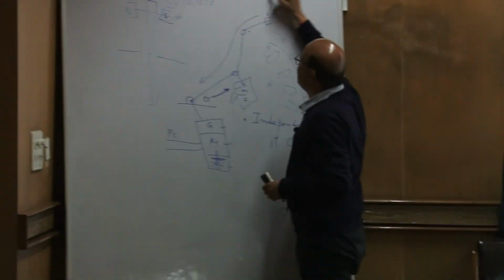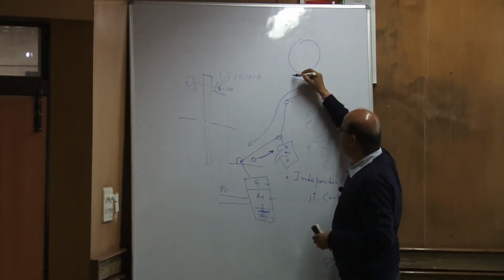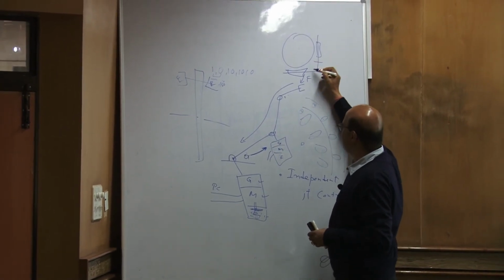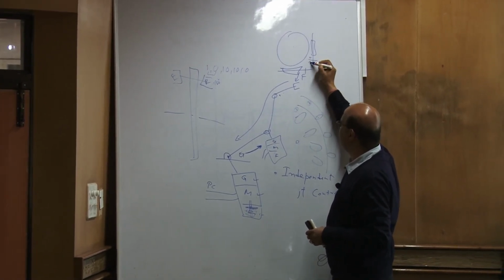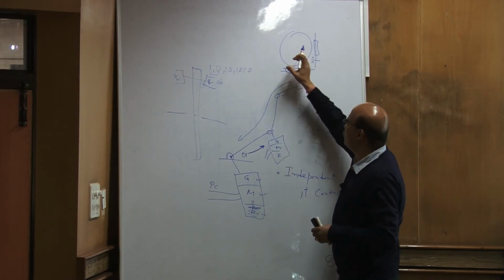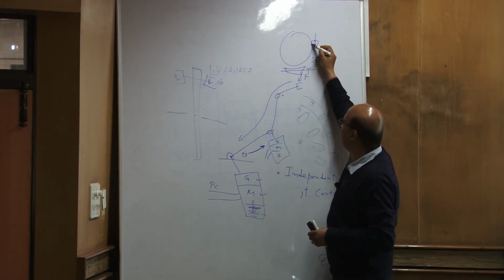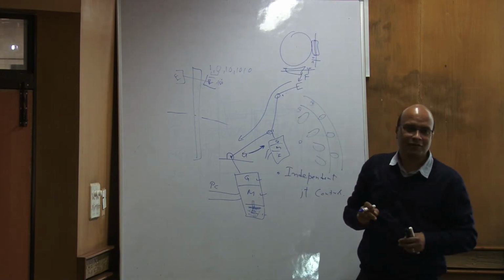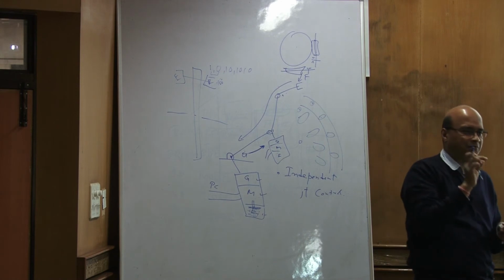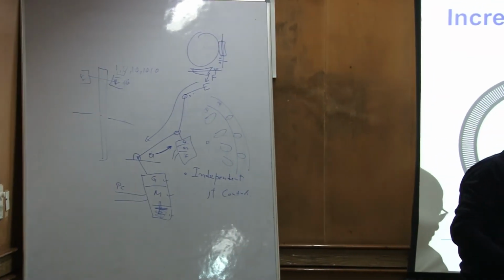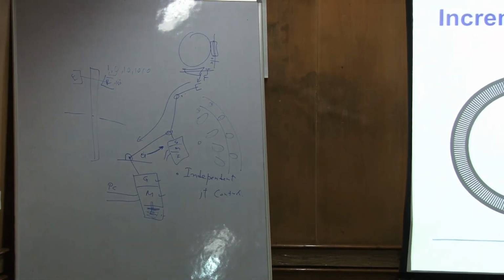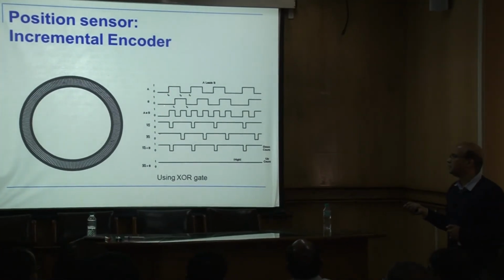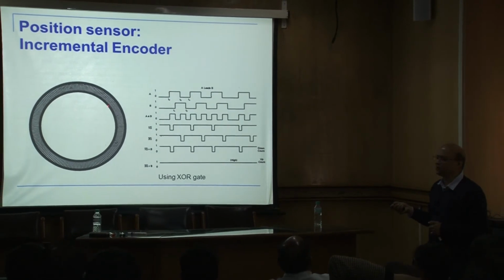And on the side of the mouse, there is a roller here, and there is a roller here. Right? And on the roller, there was an encoder here and an encoder here. So there is an emitter, receiver, emitter, receiver. So when you move the mouse, what happens? This is in contact with the ball. So this one rotates. If you move it like this one rotates. That's how it used to sense position. The olden day mouse. Now it is optical. So exactly the same principle is used in measuring position using an optical port.